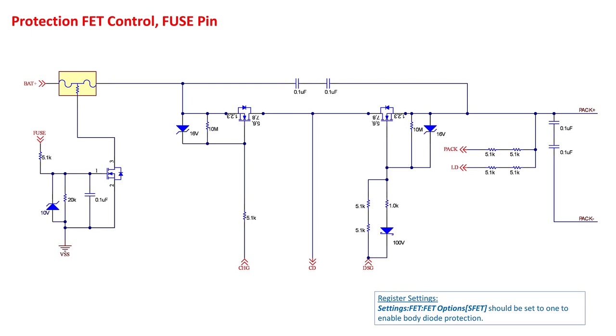When the device is put into shutdown mode, the charge and discharge pins are allowed to fall to VSS, but in this circuit, the Zener diode and the 10 megaohm resistor will hold these pin voltages at the battery voltage level. The typical recommended 10 meg resistor results in a 1.1 microamp load when the charge pump is enabled. Using a smaller resistor value than 10 meg increases this load, which could pull down the charge pump voltage. Sections 7 and 8 of the multiple FETs application note discuss the charge and discharge driver in much more detail.